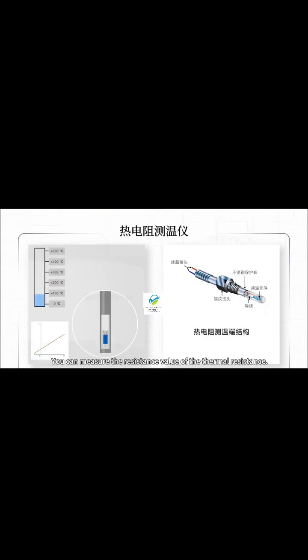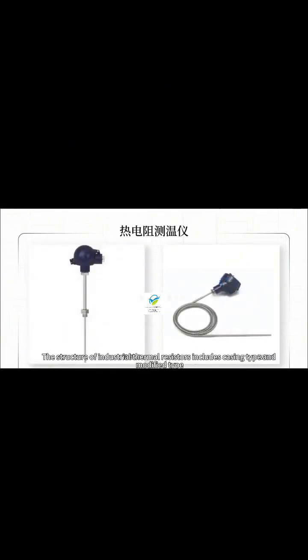The thermometer makes a spiral of a bimetal plate, and when the temperature rises, the metal plate rotates to drive the dial to rotate at a corresponding angle. The overall structure is simple. The environment is adaptable, cheap and durable. Overall, bimetal thermometers are simple in structure, low in cost, do not require a power supply, and have moderate accuracy. It is commonly used in routine in situ applications.